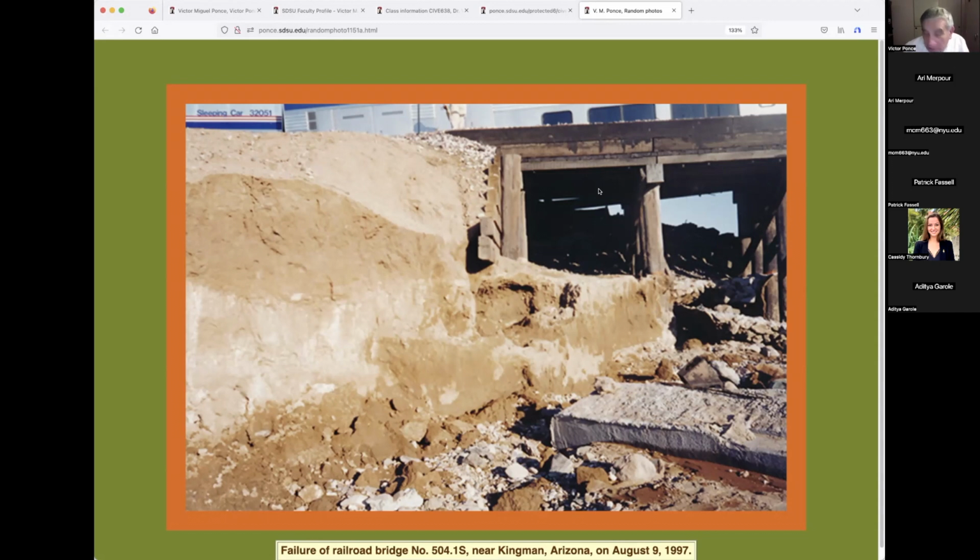How deep was the pile? I don't know exactly. I don't remember at this point, but I'm guessing that below the grading here, it probably was 4 or 5 feet, 6 feet high. I mean, deep in there, and it failed. And it failed because there was a hole in there, a scour hole during the event, which of course, after the event doesn't show up. Like I already told you, it fills up.